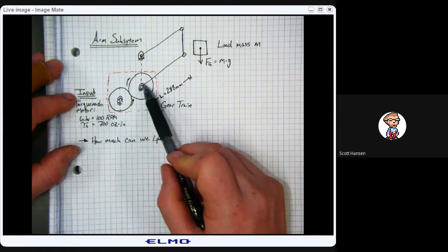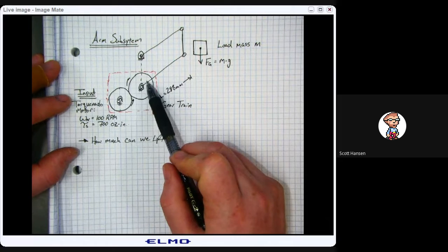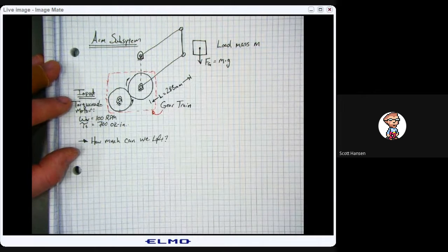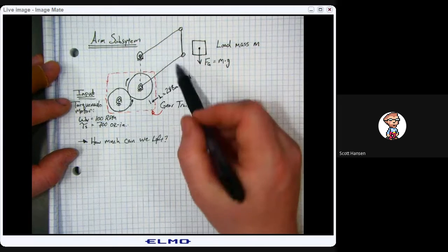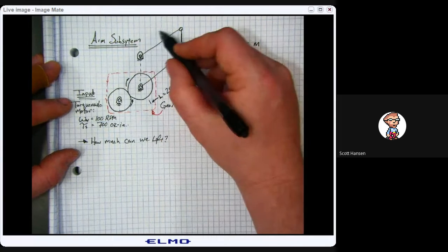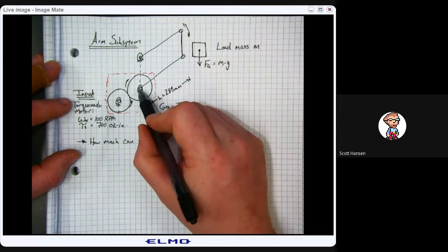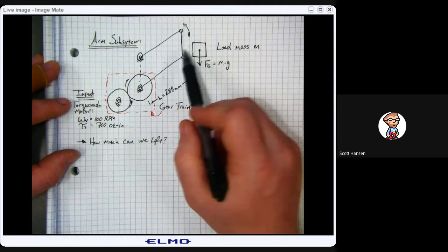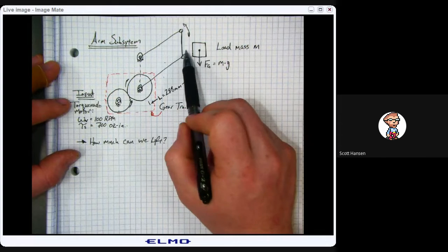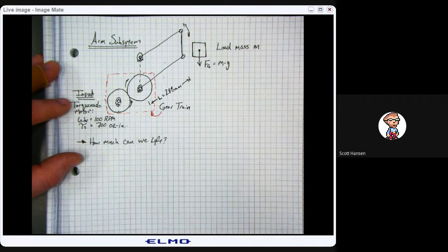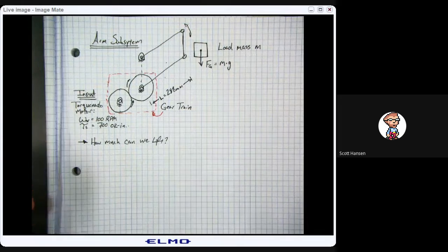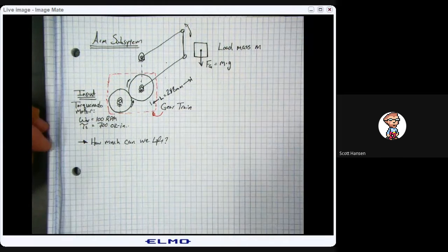And then this is a pretty standard 4-bar linkage mechanism. This thing can move up and down relative to this pivot point, and these parallel bars keep this segment perpendicular to the ground. So it's a nifty type of mechanism for being able to lift something up and down.